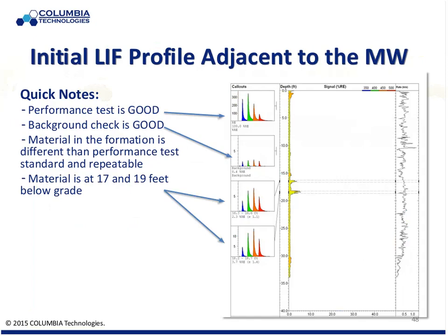Okay, here's a similar situation. Not an infrequent call, similar to what I talked about earlier. The wells were clean for years. Now the wells have oil in them. Where did the oil come from? Well, so you got oil. We'll start with laser-induced fluorescence because it's only supposed to see oil. We'll go out, push the LIF adjacent to the monitoring well.